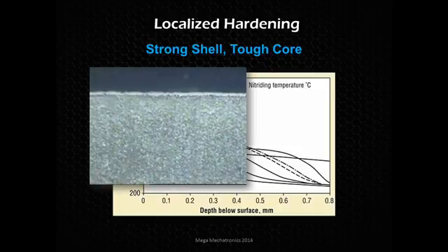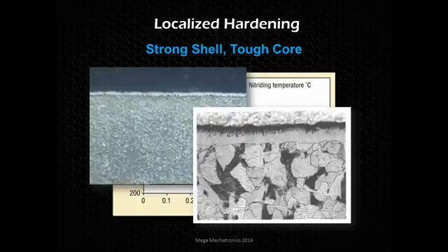And here's a close-up view. You see that white layer is a different crystal structure, so it looks a little different. And as we're getting up a little closer, you see those grains, the light grains and then the dark, and those are different alloying elements and things like that. And then you can see that nitrided layer with, again, a different structure and smaller grains. You can't see the grains.